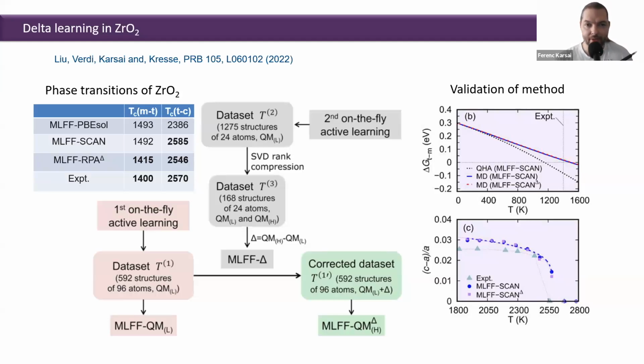So we had small bugs. In principle, everything should work out of the box, but we had some bugs in the main loop. But I think now even IBRION 5 and 6 work. This means IBRION 5 and 6 are finite differences for phonons. So you can use this for relaxation, phonons and molecular dynamics. So there it really makes sense to use the latest version and keep an eye on the known issues, perhaps on the wiki.